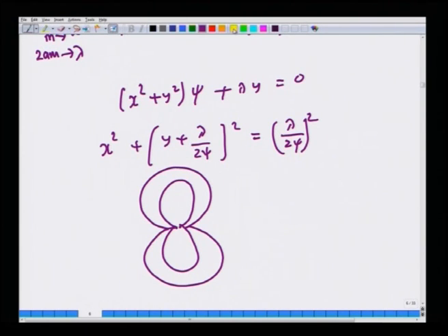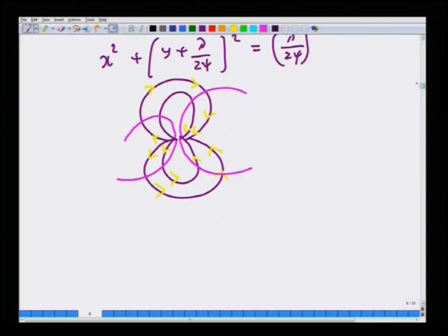So, essentially the source will tend to push the fluid in this direction, the sink will tend to attract the fluid in this direction. So, the direction of flow is like this. The source is trying to push the fluid like this, the sink is trying to attract the fluid, and the equipotentials will be perpendicular to this. Okay. So, we have to draw circles that are perpendicular at each and every point, and so on. Okay. So, those are the equipotentials, and the potentials are also easily derived for the doublet.